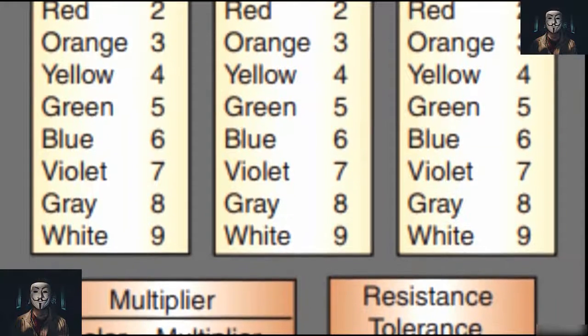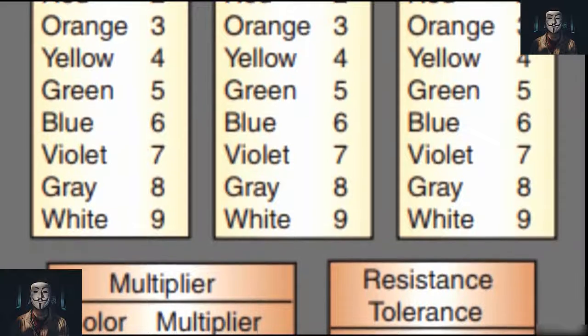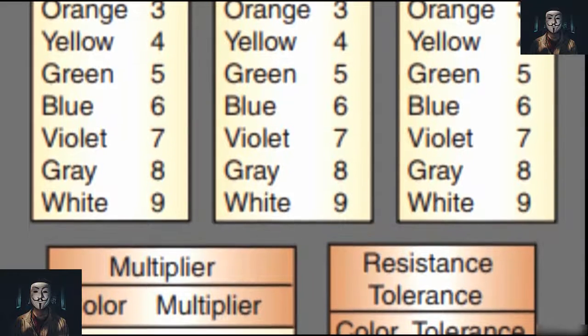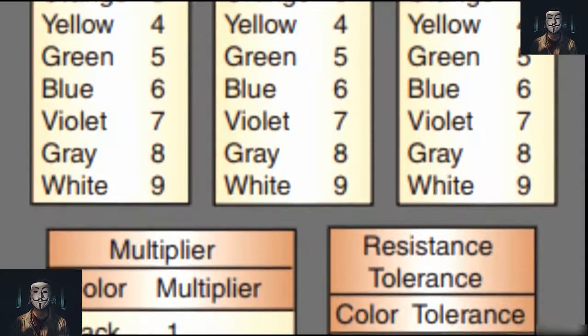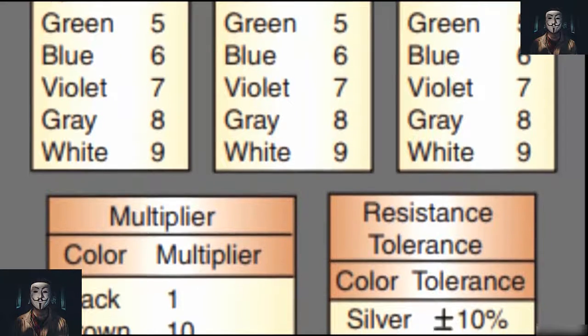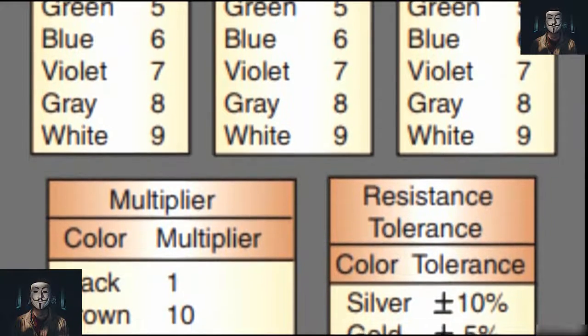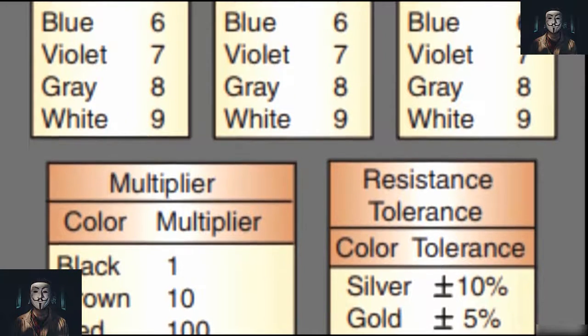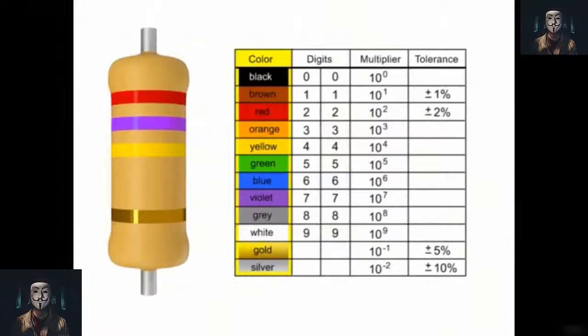Stepped resistors. A stepped resistor has 2 or more fixed resistor values. The stepped resistors can have an integral switch or have a switch wired in series. A stepped resistor is commonly used to control electric motor speeds. By changing the position of the switch, resistance is increased or decreased within the circuit.